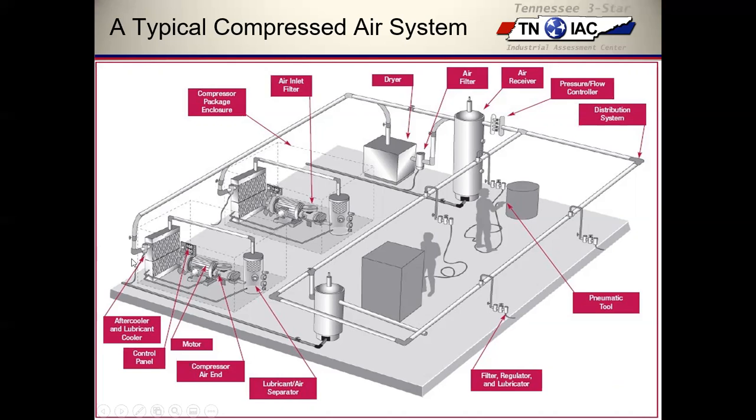Notice we do have these long radius elbows coming in here, which is a best practice. We'll talk more about that in the piping portion of the discussion. We're feeding down here. This would be a valve to be shut because we would want to go through the dryer. We got filters, moisture separators, and I'll show all of them here. Would come back up to the compressed air storage tank, to have some air stored to smooth out